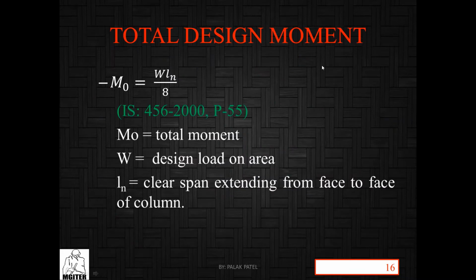Now we have some total design moments. First, the design moment is W ln by 8, from IS 456:2000 page number 55. These are the flat slab design moments. M0 is the total moment, W is the design load on the area, ln is the clear span extending from face to face of column. Clear span is from face to face of column, right?